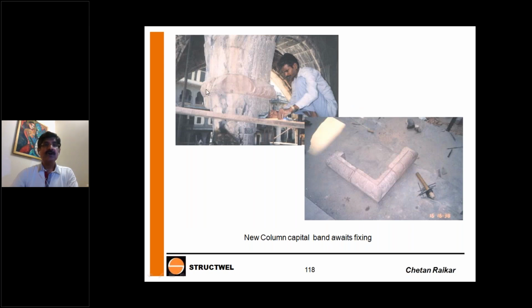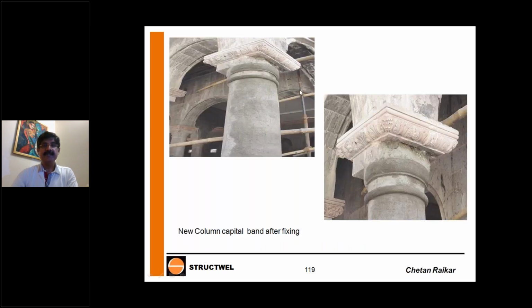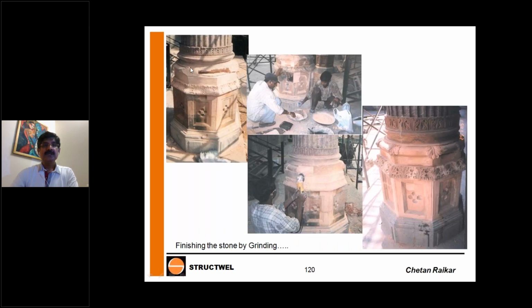This is where the cornices were broken because of fire. This is how stone cornices were created and fitted into this. This is how it looks completed. Partially damaged stone was repaired using plastic mortar. Plastic mortar is lime, a little part of cement, stone powder of the same stone, non-shrink additives, water, and a little surki. If you don't mind the reddish color that surki gives.